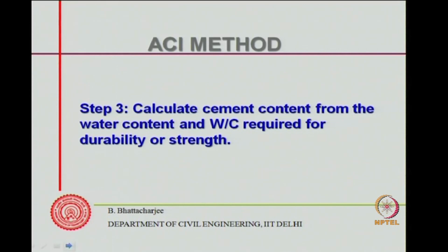The DOE method used the wet density concept, while the IS method used total volume: the sum total of volumes must equal 1 cubic meter. So, the conservation of volume principle.